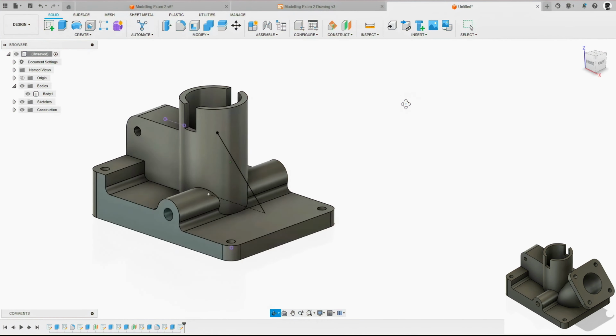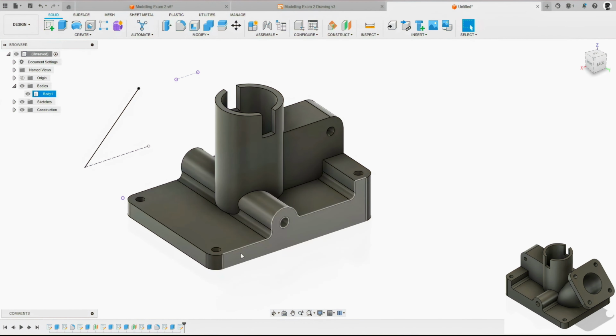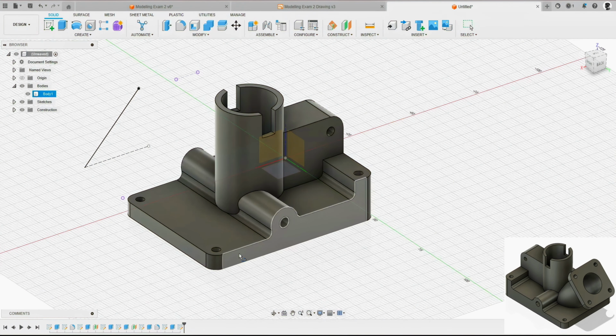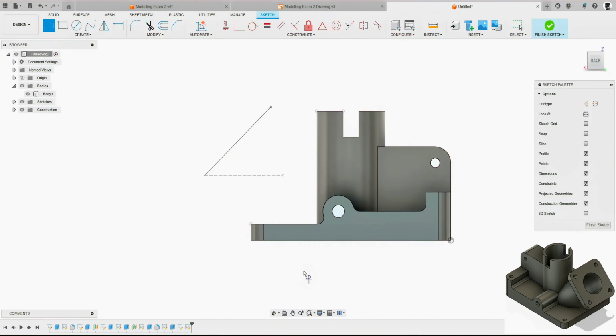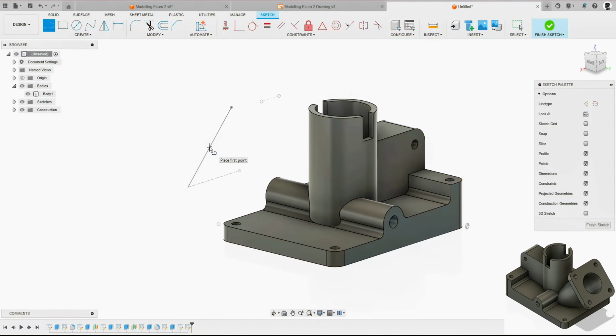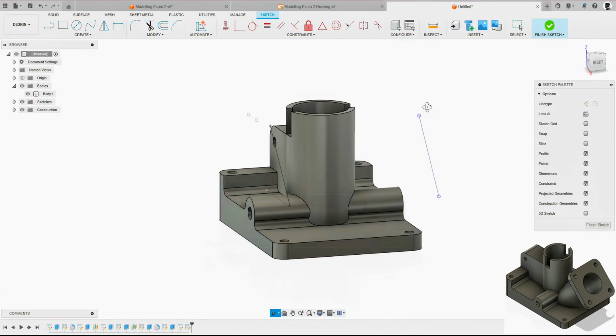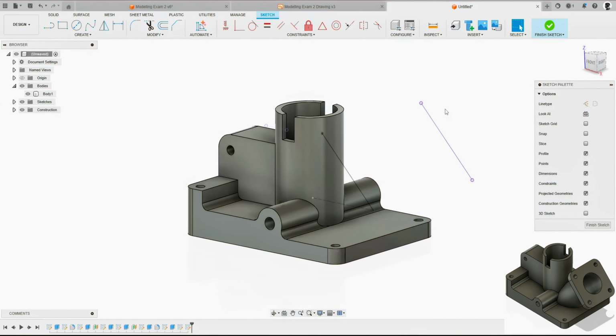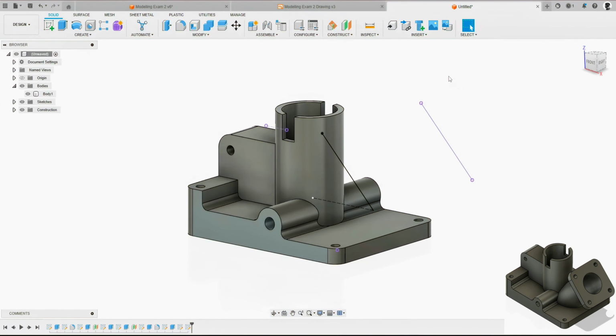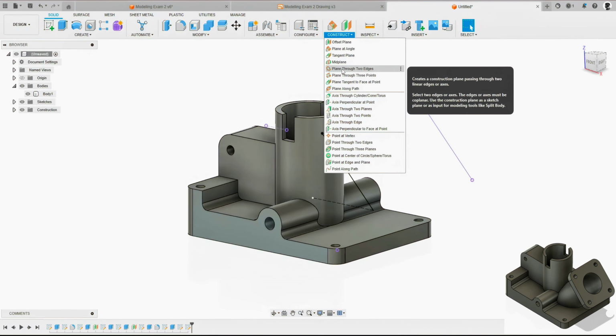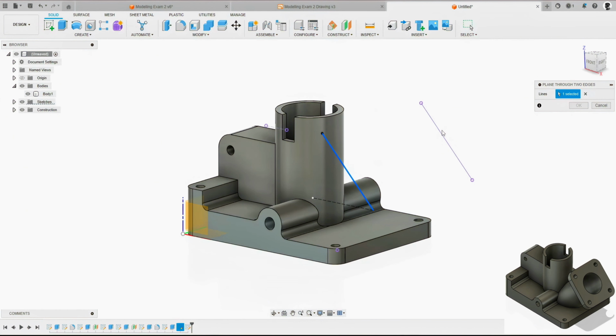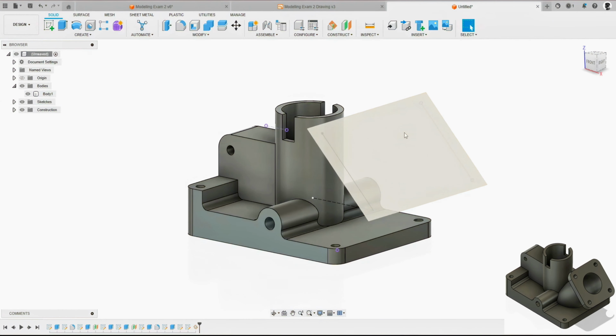Let's finish that sketch. Let's create another line on this face here. So let's go to L on the keyboard and select this line here. And we could just project this existing line. So let's hit P on the keyboard and select this line, press OK. Now we've got these 2 edges here. We can form that plane. So let's finish the sketch. Come under construction and go plane through 2 edges. We can select these 2 edges here, press OK. And from here we can start sketching.